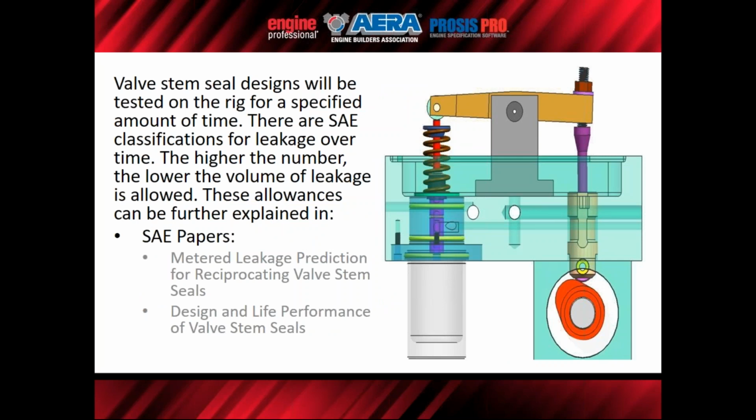So this is a cross section of what it looks like within that machine. The test rigs will have the customer's guide, and typically this stuff is at the OE level, but some of the reman facilities are having to do this too. A good example, one that I personally was involved in, was a 3126 Cat, and they actually have two different groove depths on the ID of the guide. Then you start playing around with oversized stems, and you change the groove depth, and then you impact the stem seal itself.